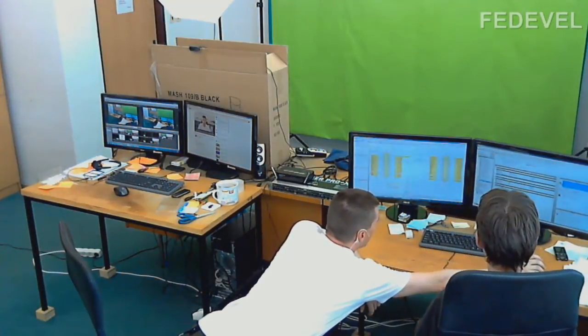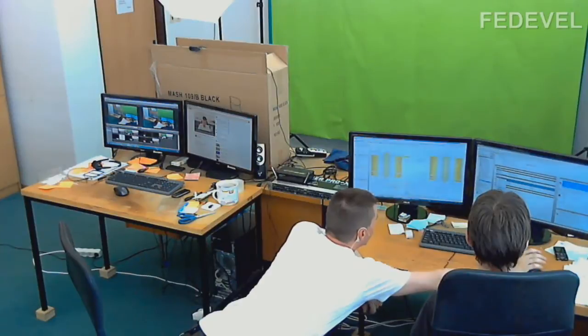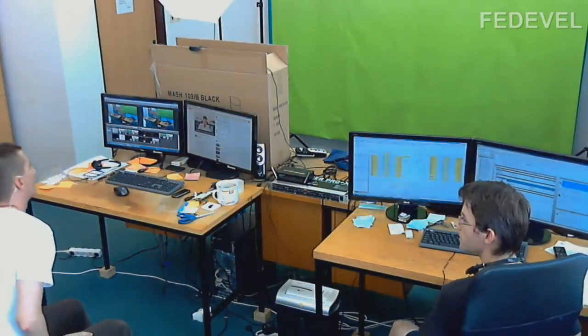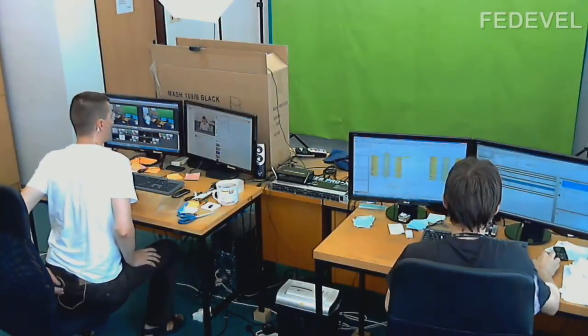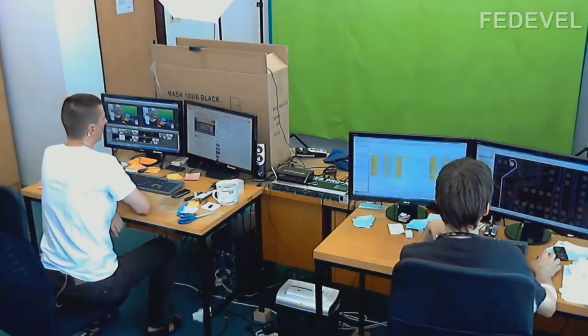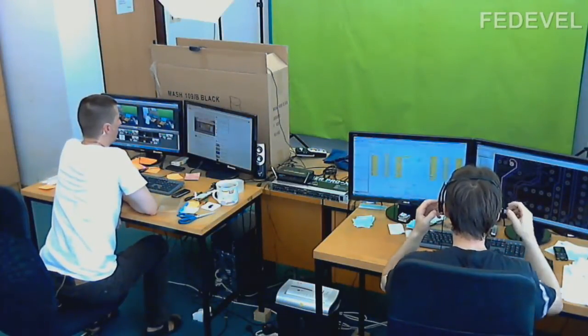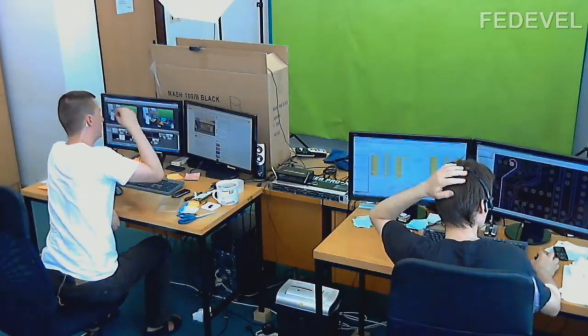So normally I use Gerber files and ODB++ files. These are accepted by manufacturers for PCB manufacturing, and for board assembly, of course, you also need to generate NC drill files for the drilling.